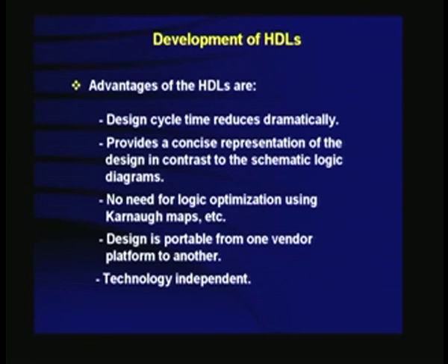As I said, HDLs have many advantages. Design cycle time reduces. It provides a concise representation of the design in contrast to the schematic logic diagrams. No need for minimization, all that is taken care of. Design is portable, that means I can have a design description and use one particular FPGA, and if I am not happy with that particular vendor, I can go to another vendor and use the same description. Of course, I may have to recompile it for his device, but it is possible. And it is technology independent. It can be 70 nanometers, or it can be 1 micrometer. I can still use it.